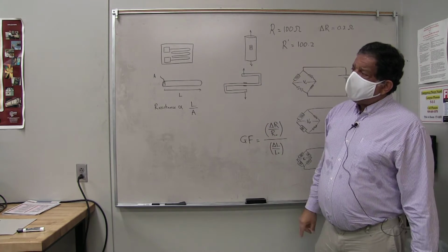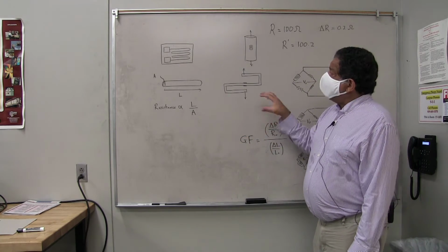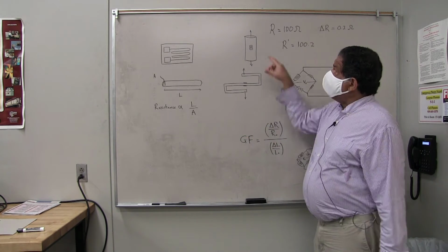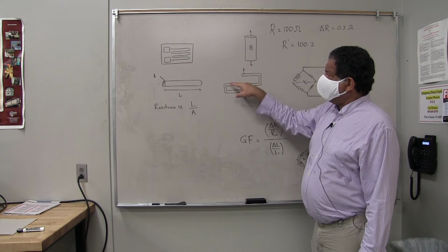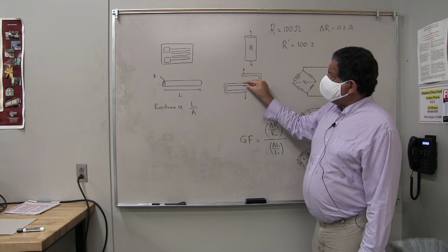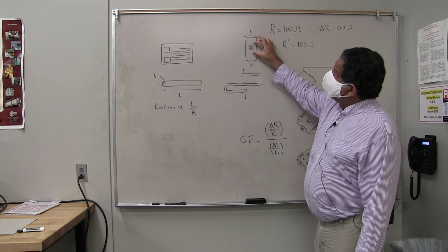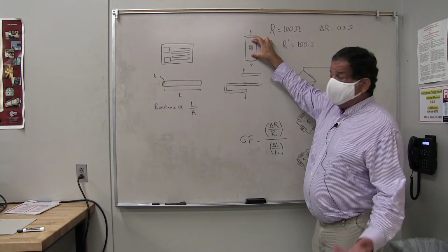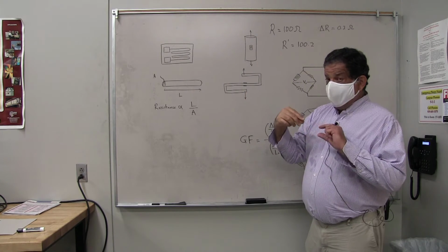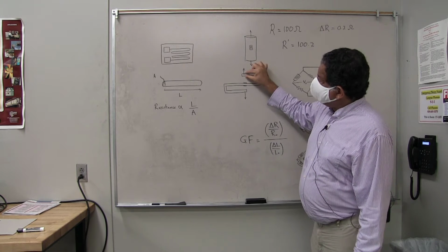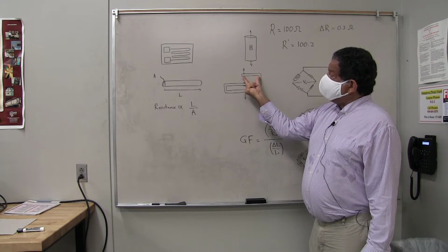So in the load cells on our testing machines, what you will see is that inside the load cell, they don't have just a straight tensile member. They'll have a beam that is bent like this with strain gauges on the top and the bottom. And then essentially when you apply the same load, this thing is just going to stretch directly in tension. But here you have a bending moment that has a mechanical advantage basically of this cross-section divided by that length, right?